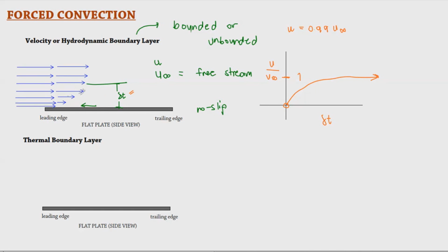And then you might be wondering why we're actually having more velocity here. The velocity is able to overcome this because the resistance offered by the layers that are here will be much lesser, since the resistance would be coming from the fluid itself here. So it's getting diminished as it goes farther away from the flat plate. So that's it for our velocity hydrodynamic boundary layer.